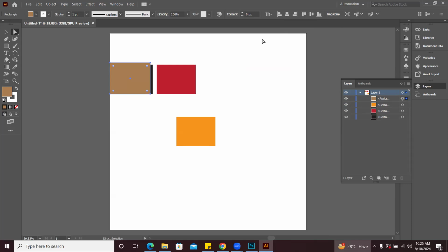The artboard is the area where I am drawing all of the things, so I can change its size depending on my requirement. If I make it center aligned, you can see that it has horizontally aligned itself. If I align to the right, you can see that it is horizontally aligned to the right. Similarly, you can vertically align it to the top, to the center, and to the bottom as well.